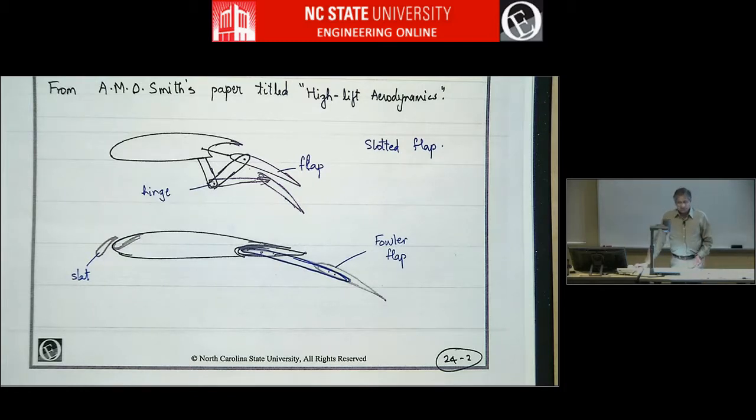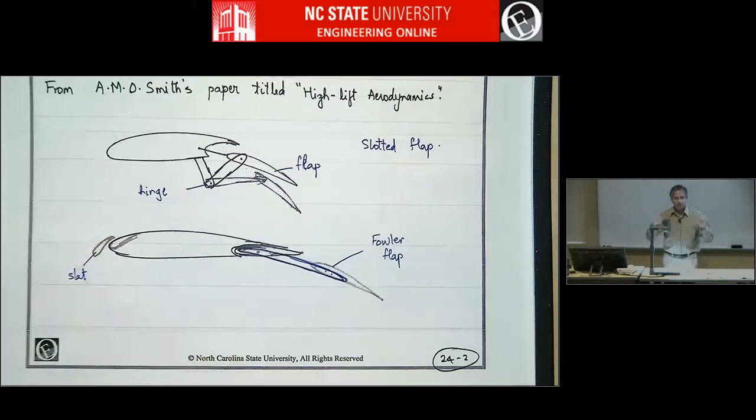But there were a few airplane designs, and I don't think they do this anymore, but back in the 1920s and 30s, like the de Havilland Tiger Moth, I think is an example, where the slats are spring loaded, and at high angle of attack, there will be a lot of suction here, and the suction will cause the slats to automatically pop out exactly when it's needed. It's at high angle of attack that you need it. And when the suction goes away, the spring will pull it back. So the pilot didn't have to do anything, which was a pretty clever idea.